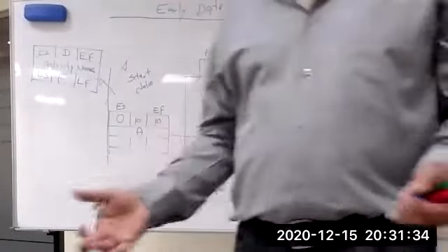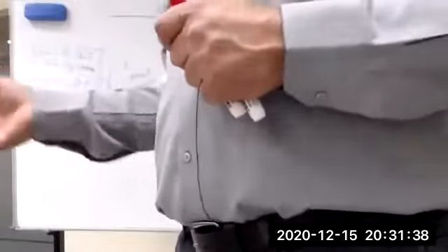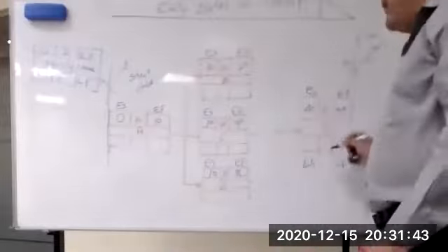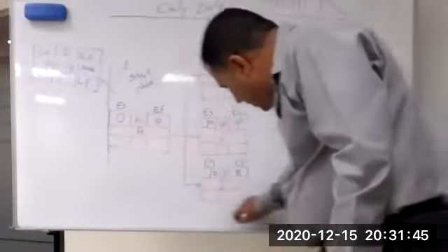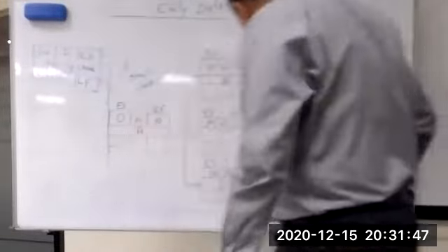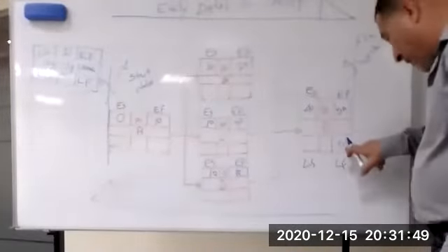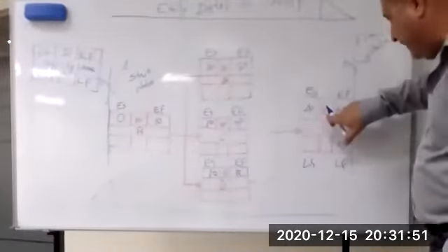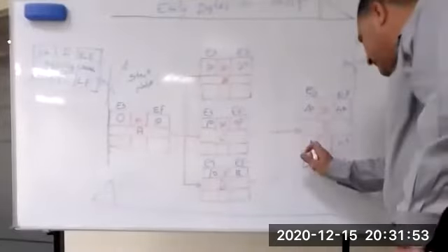The last activity cannot have 2 dates: late start, late finish, and early finish. Both of them should be equal. Now the backward pass. Start from here and go back. 50, see my hand. 50 minus 10, 40.